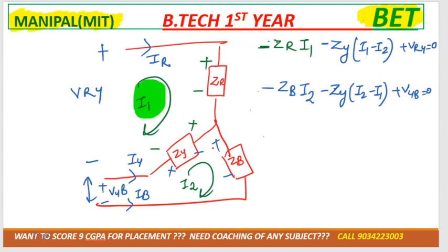We have to mark signs according to the current movement. I2 is moving plus minus and then plus minus. For mesh analysis, we have to take the second sign, if you are moving around the mesh like this. So it would be minus ZB I2 plus VYB and minus ZY (I2 minus I1). Okay? Clear?